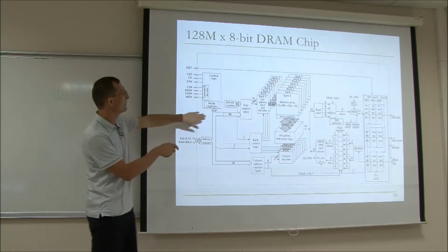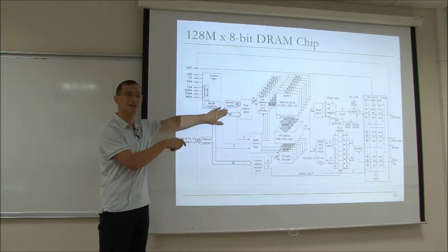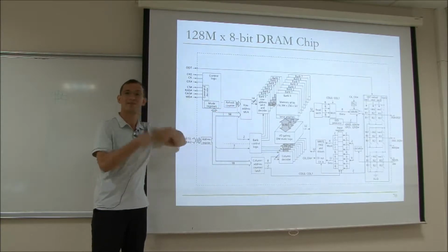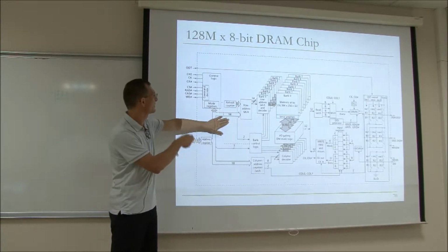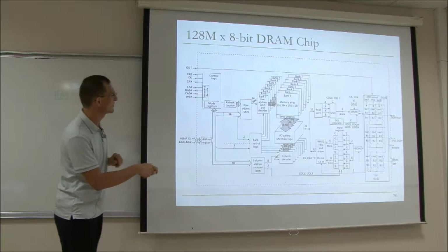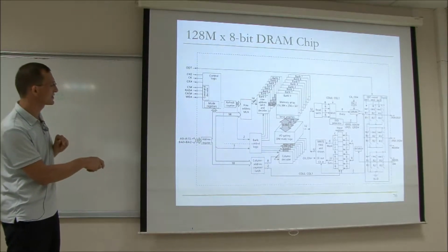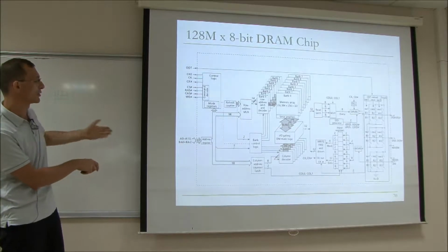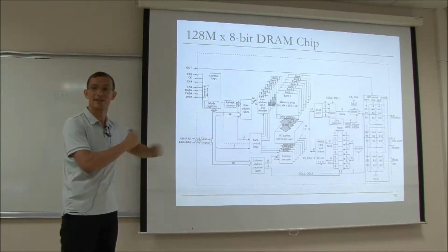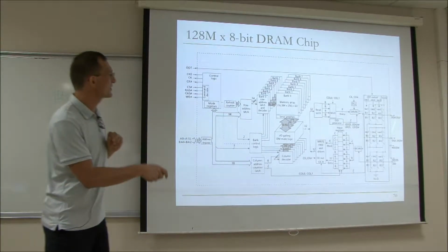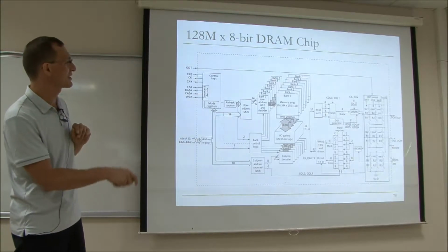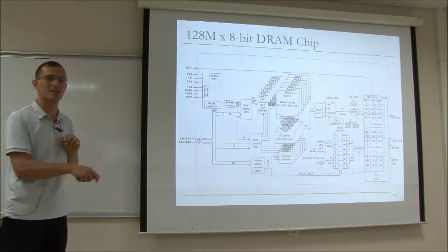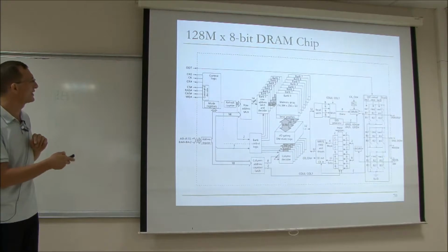And you can have refresh inside here. When the DRAM bank is refreshing itself with a command from the memory controller, it refreshes itself from here. And you have a bunch of control logic. And these are the address registers coming in, specifying the bank and specifying the row or column. And remember that those were multiplexed. And there's a bunch of termination logic that ensures stabilization of the chip, and that actually consumes a lot of the area.